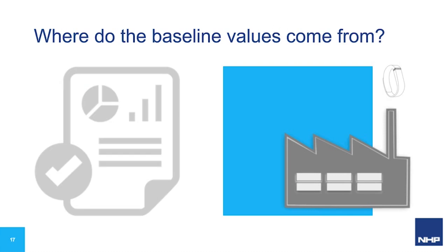Baseline values. Where do these come from? So baseline vibration values are required for an important snapshot of the relevant critical asset that we're considering for integrated condition monitoring. Now, this data is used to evaluate the asset's existing condition, understanding that we have a lot of machines that are not greenfield installs, or we have a lot of brownfield sites that have machines running. So this will also help you identify if we have existing conditions that require immediate remedial action. And if not, then we can simply use these baseline values to trend going ahead, but at least we get the snapshot of where the machine is.